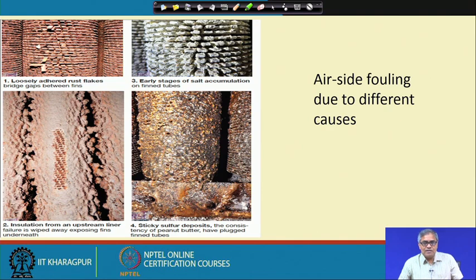So, in a nutshell, liquid side fouling is there obviously, and gas side fouling is also present, and in gas side fouling certain mechanisms are more prominent. In liquid side fouling, certain other mechanisms are more prominent, like crystallization etc., which are more common in liquid side fouling, whereas deposition, particulate deposition etc. are more common in gas side fouling.